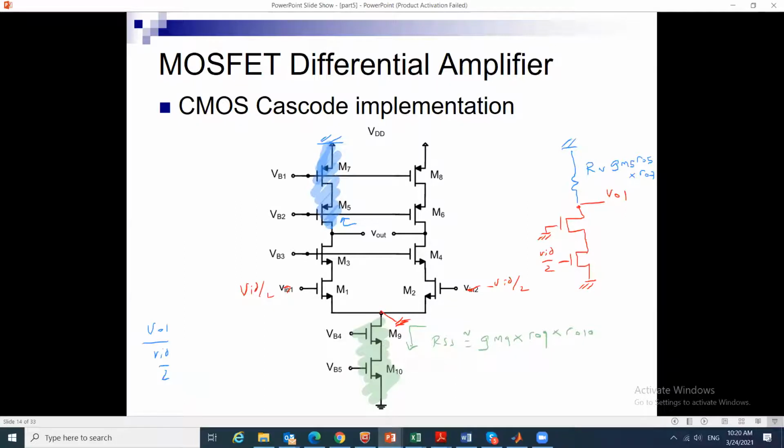The same for the right side. I break it into pieces, and of course the cascode, we did not derive it when we have resistance below my transistor, so it becomes a little bit involved for the common mode, but at least for the differential mode we should be able to know how to map it to the existing formulas. Okay, anybody has any question?